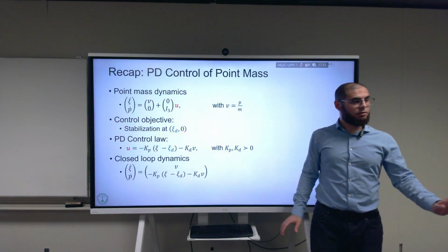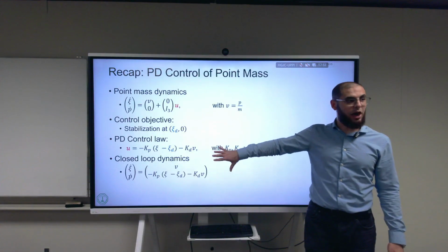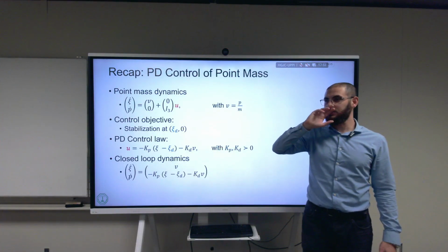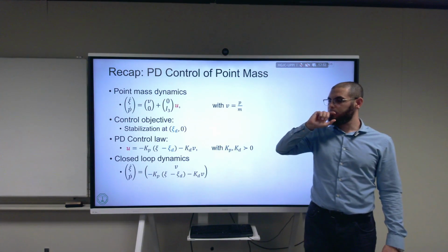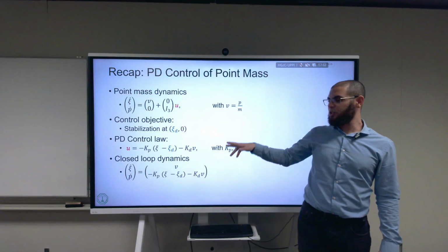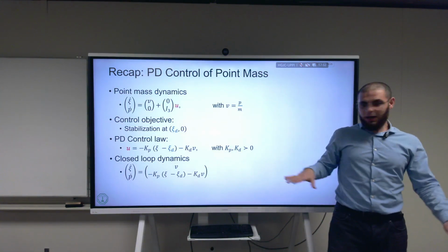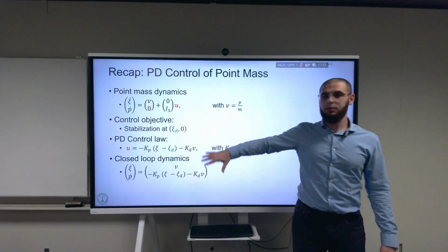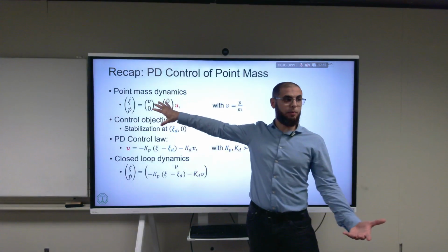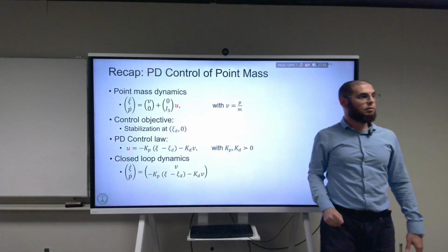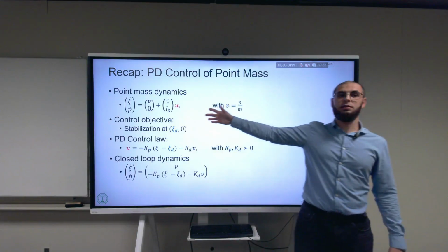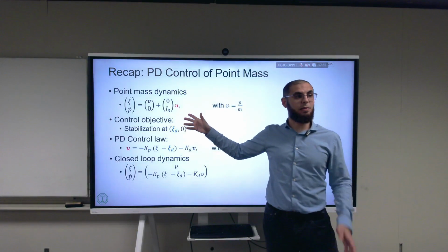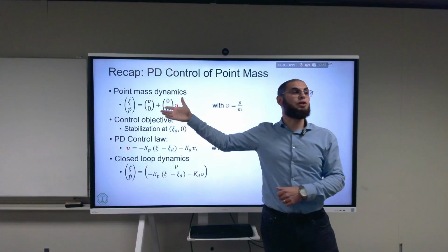That's an excellent question. So why would we not look at the I term? Let's keep that till later in the lecture. I have to mention it later on, but not now. For now, this is just a theoretical system, a toy problem, theoretical on paper. This only works when we have 100% correct dynamic knowledge, absolutely, and no disturbances here. If you had disturbances, the I term is just for the disturbances, not to stabilize the system.